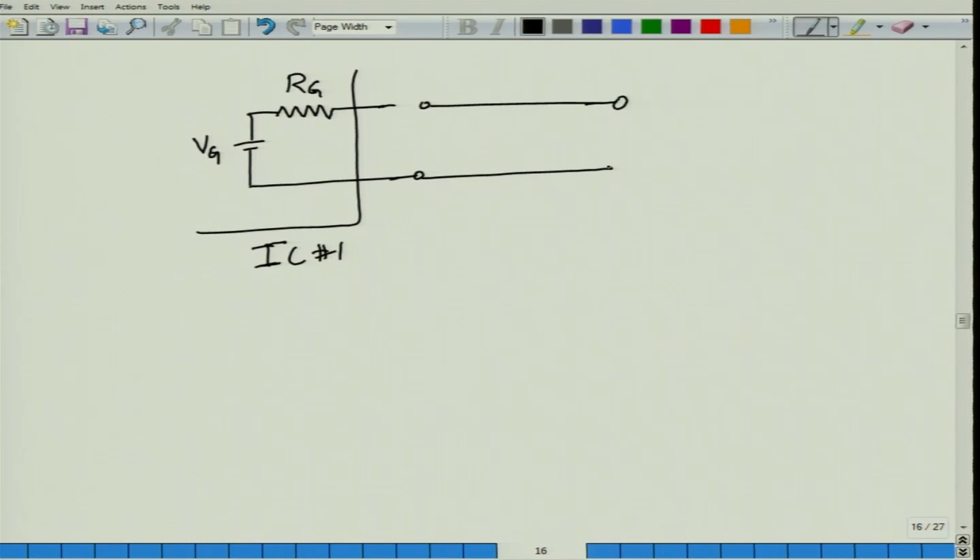So, this transmission line of course is not intended, but it is actually the artifact of a wire not being a wire actually. So, this would be, let us say, terminated in a load of some value RL. We will also assume that the transmission line has a certain characteristic impedance which is R0. Now, let us watch what happens. We will not connect this one to the transmission line.